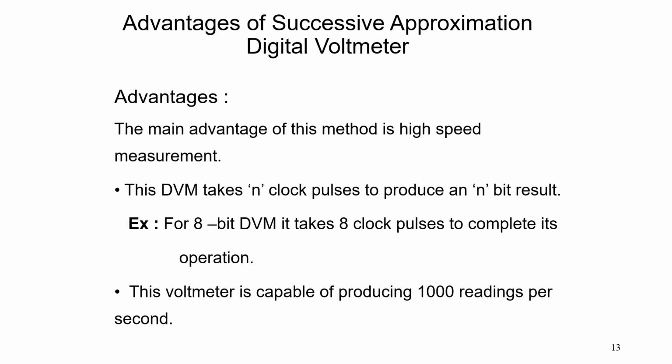When the ring counter advances by 1, the third MSB is set to 1 and the converter output rises by the next increment of half plus 1/8 V. The measurement cycle thus proceeds through a series of successive approximations.